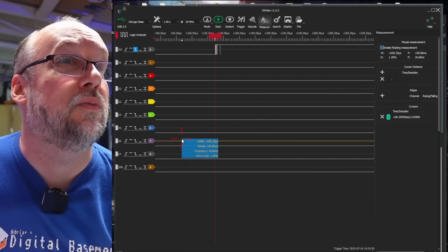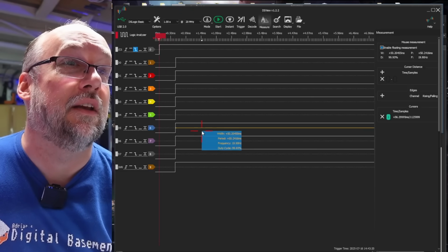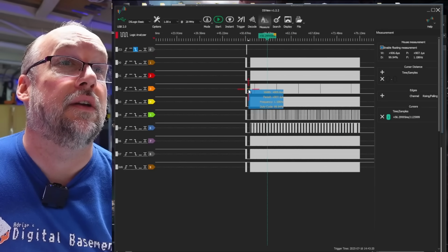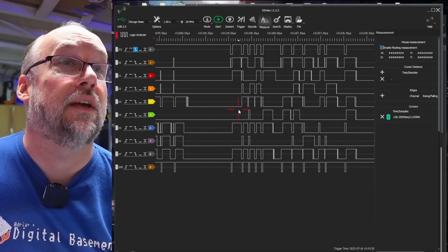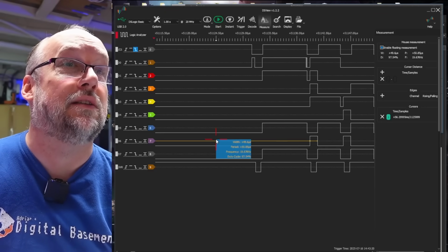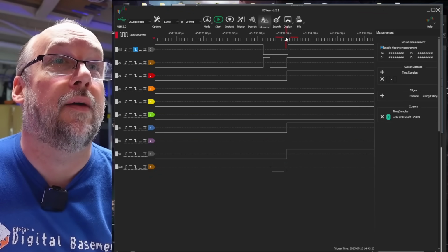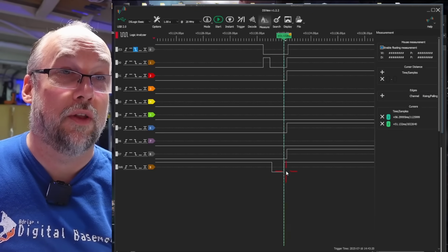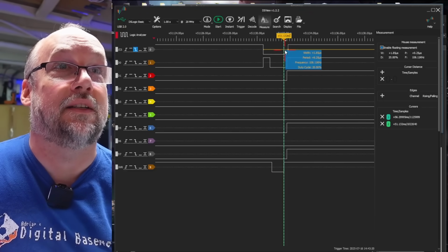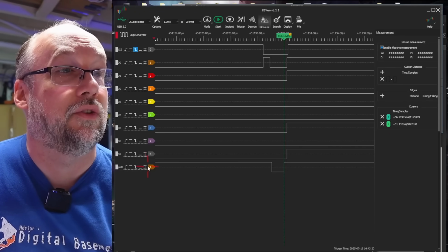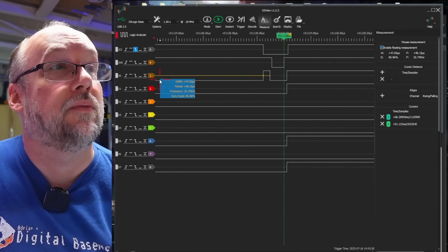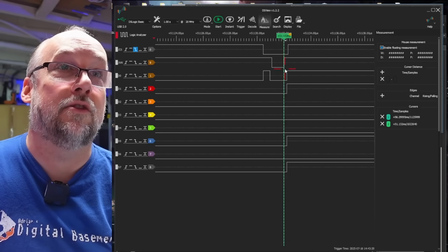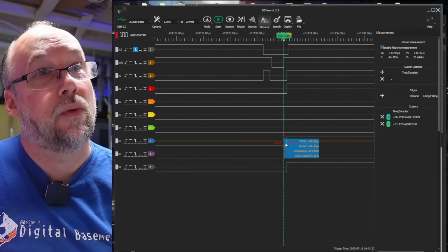Okay. I gotta zoom out because we have a little bit of junk at the beginning as the system sort of sets up and starts booting. I think right here is what we're concerned about. Yes, it is. Okay, so this is the right signal. So let's zoom in. I'm pretty sure it's right there where the CRT controller, where the write signal goes high while chip select is asserted. In fact, we could just move this up. Let's move this up there. Right, okay. So chip select is low and write was low and then goes high. And that's where it's capturing the bus.